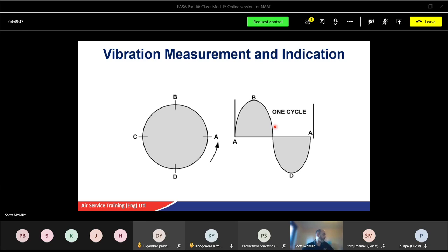Vibration. So, especially on piston engines, lots of vibration, turboprops, a lot of vibration, and even standard jet engines, you're going to get vibration. Purely by the flow of the gas going through, that will cause problems. So during the manufacture of a gas turbine engine, you've got to pay special attention to specified tolerances, the balancing of the shafts, the fitment of the blades themselves and the fit to compressors and turbines. They are set in a specific location. Each blade will be weighed.